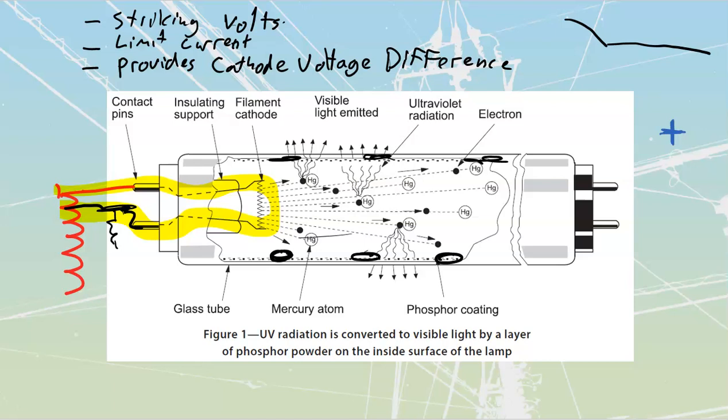We do have a couple of other ones as well, VHO and SHO, for very high output and super high output. Those are types of fluorescent lamps that operate at incredibly high values of voltage. If you see VHO or SHO, be very careful working around them, because it's going to hurt a lot if you get shocked off one of those.